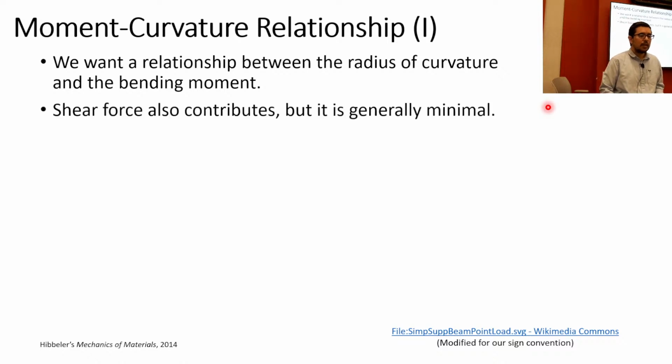Now, we have, at this point, established that moment and curvature are connected. Shear force can contribute to curvature, but its effect is quite small. So we normally don't think about shear force unless we're thinking about it with respect to moment. Next, when you take design of mechanical components, you will be able to calculate deflection due to shear force, and you'll see that it's very, very small.